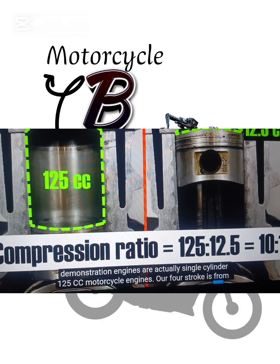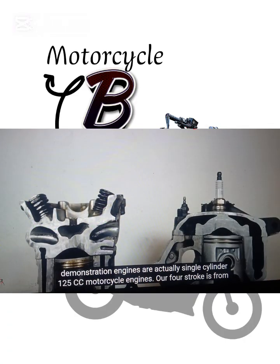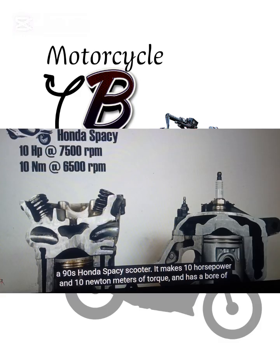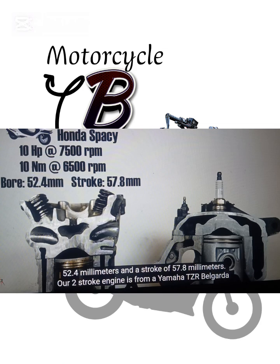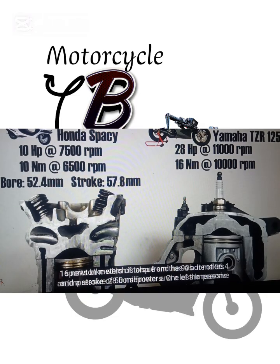Now, both of our demonstration engines are actually single-cylinder 125cc motorcycle engines. Our four-stroke is from a 90s Honda Spacy scooter. It makes 10 horsepower and 10 newton meters of torque and has a bore of 52.4 millimeters and a stroke of 57.8 millimeters. Our two-stroke engine is from a Yamaha TZR Belgarda sports bike, which is also from the 90s. It makes an impressive 28 horsepower and a less impressive 16 newton meters of torque and has a bore of 56.4 and a stroke of 50 millimeters.